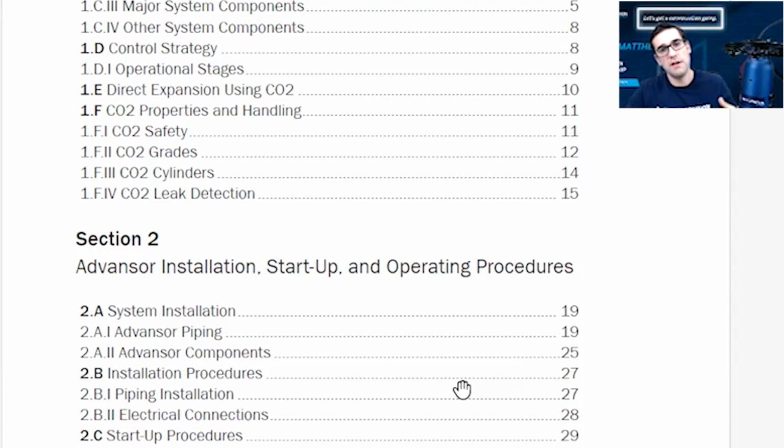But is it from the transcritical side defrost? Is it from the low discharge compressors defrost? There's different ways of doing it. You could even take it from the flash tank. I don't know if anyone has that design. I think there may be a design or two, but you really want to understand how you're doing it.